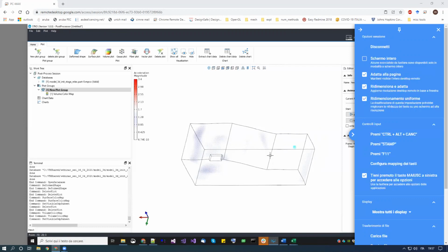So this is another question. I see. Usually I couldn't run OpenSees with zero length. Maybe it was my mistake. Probably when you use zero length elements with a finite length, the only problem is that it gives a warning, but that warning is not an error.